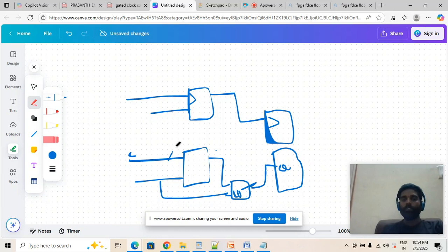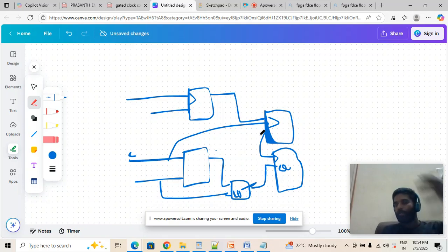This clock will again be connected to this register. So in this case, we are completely changing the circuit. The tool understands and applies the clock conversion. It uses the same clock from this clock to this clock only, on the input path. It adds the LUT with respect to the output. It's a gating logic, and that goes to the clock enable port. So this is how it will change.